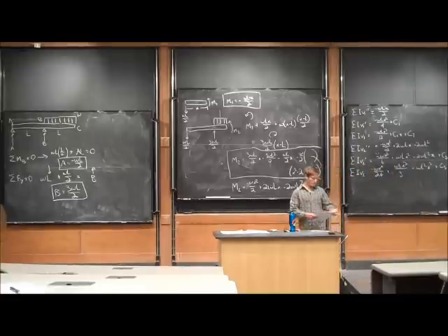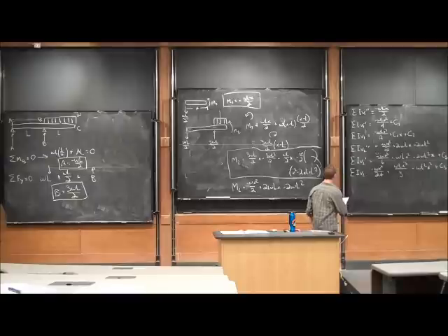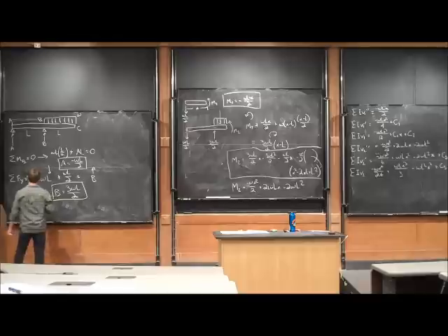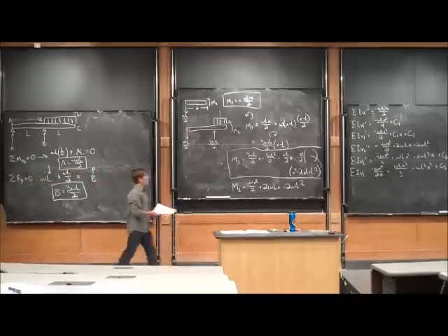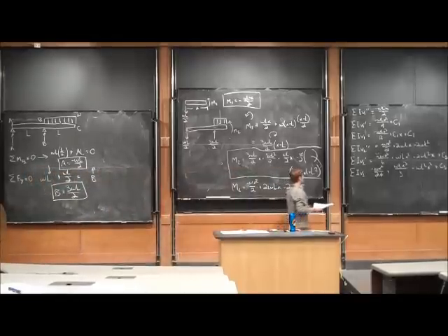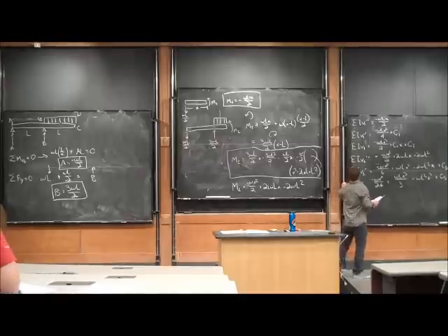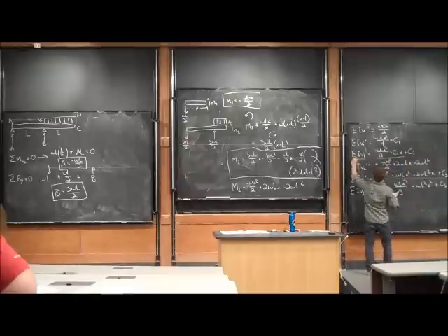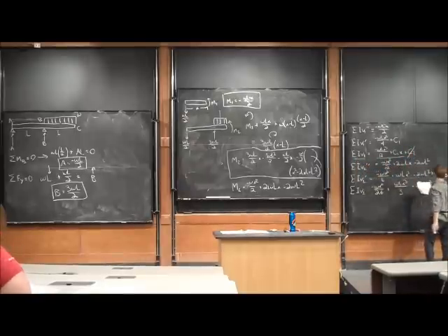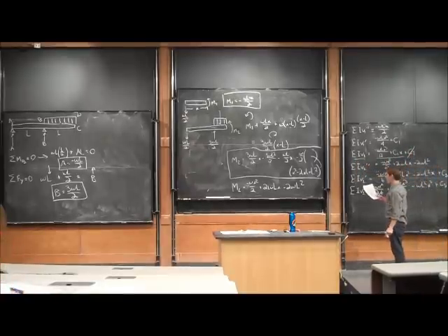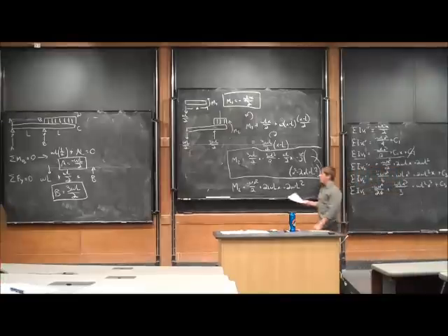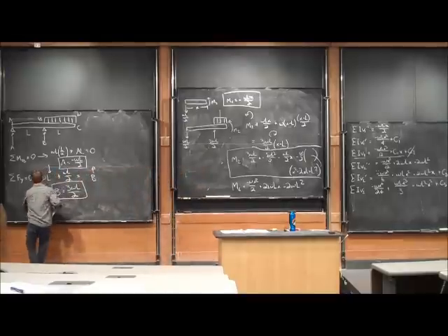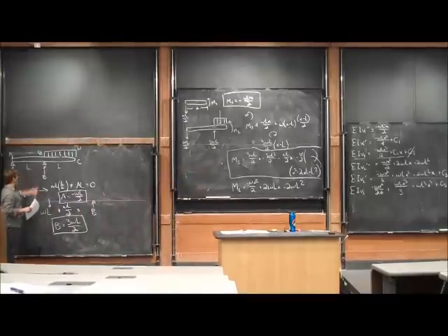So our first boundary condition we want to apply is that the deflection at x equal to 0 is 0, and that applies directly to our V1 equation, the deflection of the first half of the beam. When x is equal to 0, this term is 0, this term is 0, so we know that C2 goes away. Now we know that V1, the deflection, is also 0 at x equal to L, which is where our B reaction force is occurring.